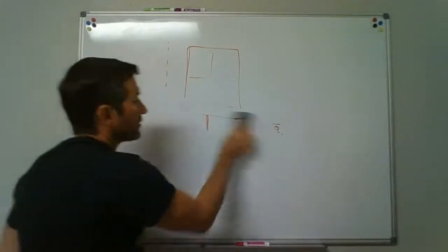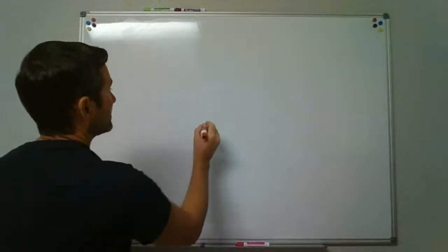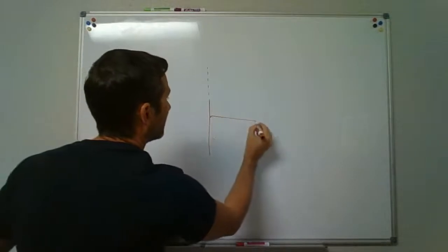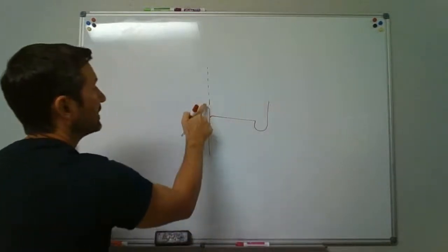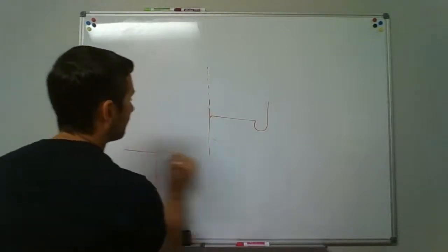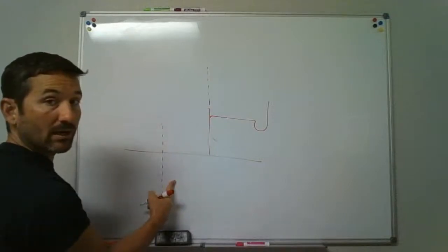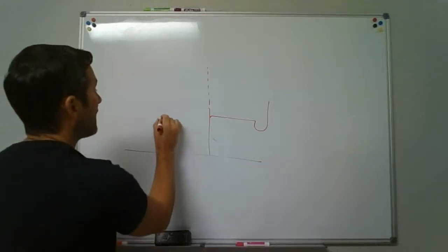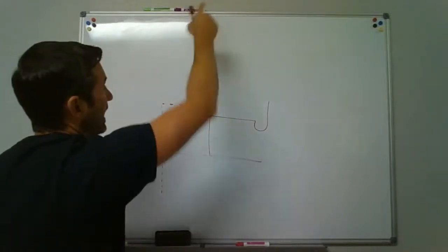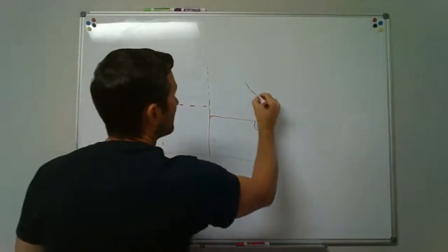Now, there was another part that was mentioned in that other section that was 6 inches. Let's just say we had, okay, there's a fixture and its vent. But now we've got, that's on one floor level. Maybe we've got a vent coming up from another, with the lower floor level. And we want to tie it back and just say, well, I'll connect it to this vent and let that vent out. Well, you can connect the two vents. That's fine.